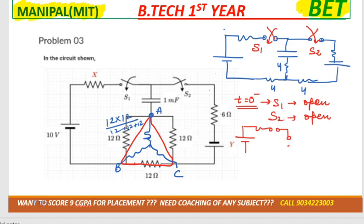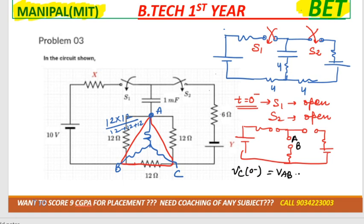It is open, capacitor will behave like an open circuit only because it's a steady state condition, everything will remain same. So in this particular condition, we need to calculate VC of 0 minus, right? As you can see that no current is flowing over there. कोई current flow हो रहा है इधर? नहीं हो रहा. So that would be 0. So from this circuit, VC of 0 minus would be equal to 0 only.